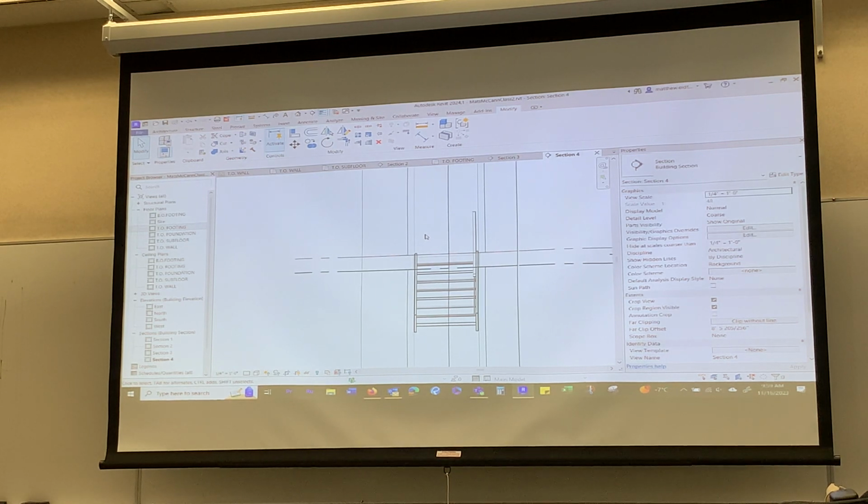To put wall rail on here is an absolute nightmare, just like it is in the real world, because there's a code for that too. 34 inches from the line of flight, which is my hip bone, by the way. I used to check that right off my hip bone, but it depends on what size boots you have on. You have to adjust for that.